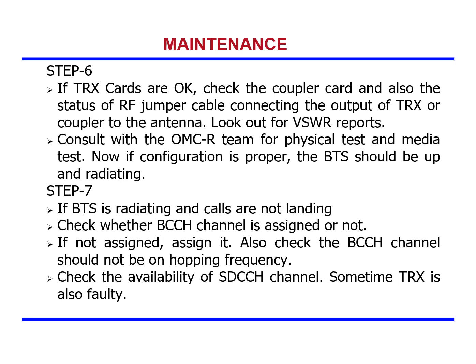Step 6. If TRX cards are OK, check the coupler card and also the status of the RF jumper cable connecting the output of the TRX or coupler to the antenna. Look out for VSWR reports. Consult with the OMCR team for physical test and media test. Now, if configuration is proper, the BTS should be up and radiating.